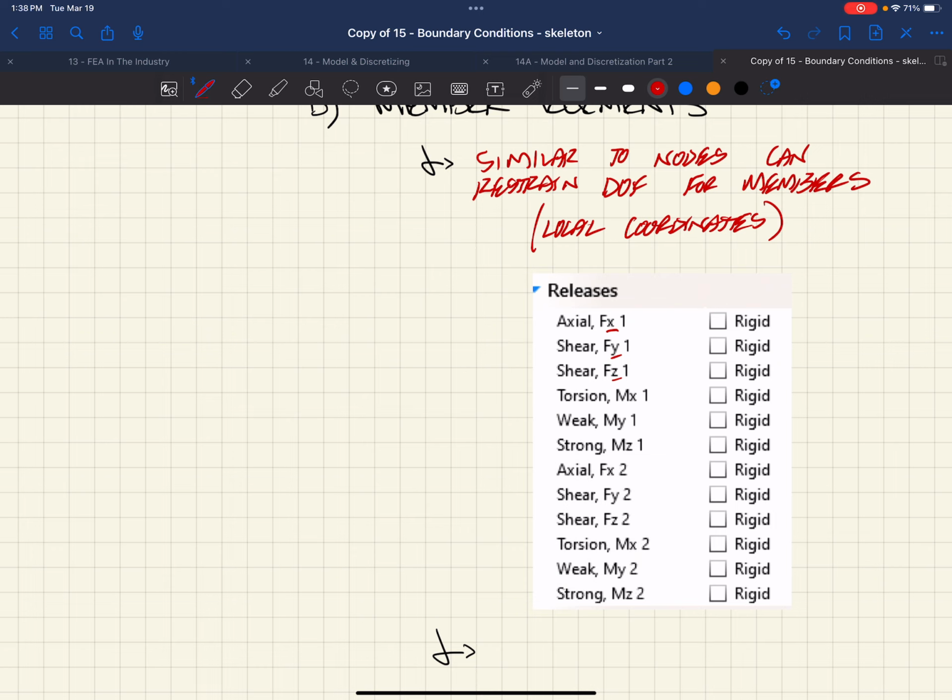And it'll go through and take those pertinent design demands in each one of those directions, and it will implement AISC 360, right, through chapter D for tension and F for flexure, E for compression, right, G for shear, and even H for combined loading, and it'll go through all of that and run through all the checks. It'll even be as specific as going through each of the equations, right, or sections pertinent to each one of those checks, so you as a designer can go back and feel confident that they're taking the right values, right?